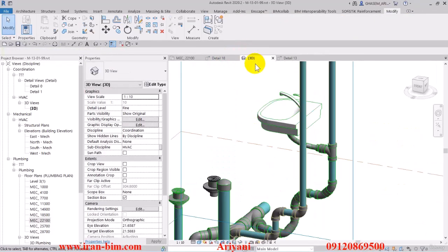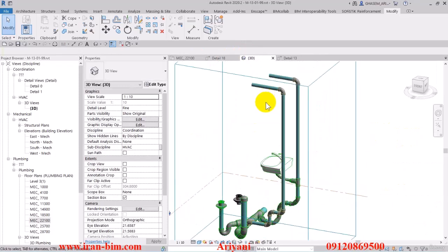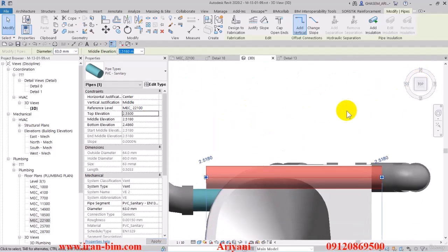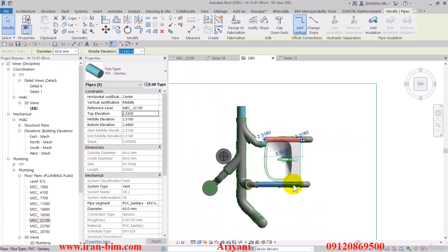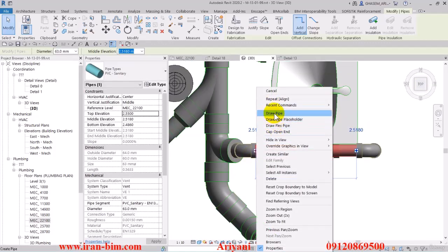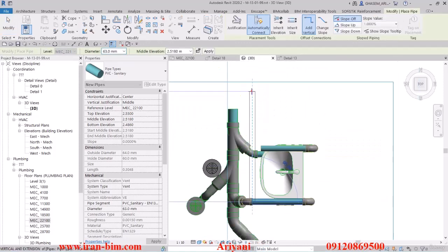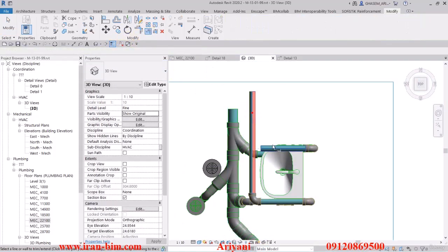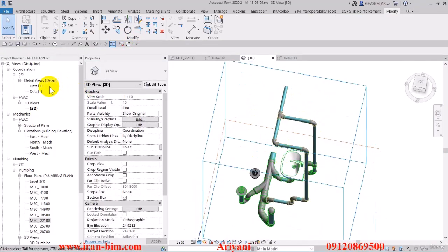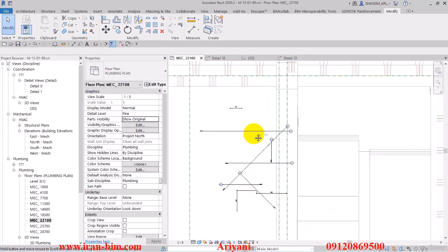So now let's see what we have for the elevation of the pipe here. It's about 2.55. So Ctrl C to copy that, and we'll give the same elevation to this one on the right so that they match up. And then we'll go over here to the pipe here and hit draw pipe, where we can draw the pipe towards the up direction, and then stop right here and then connect the system and the pipe in this point. Now this system here goes through the riser that we have located here.